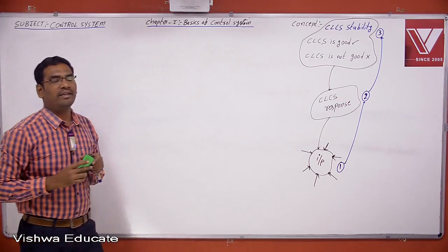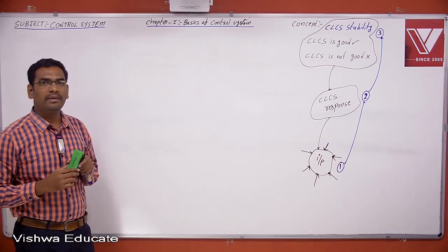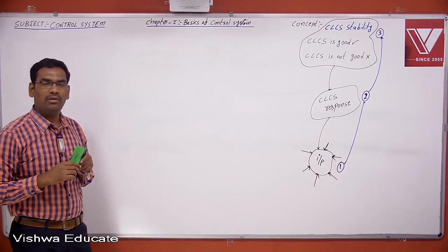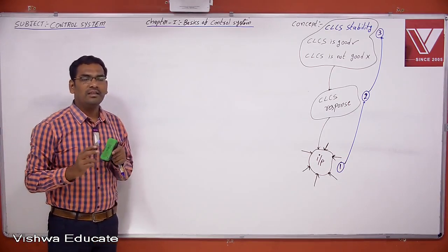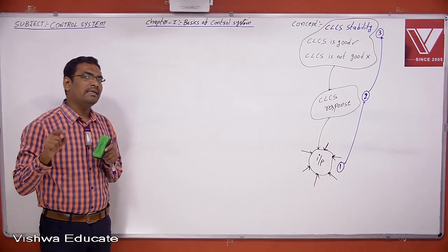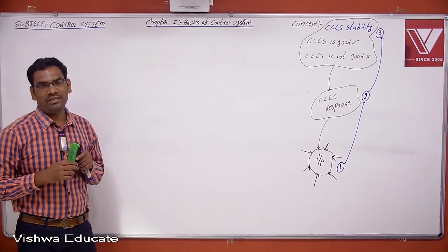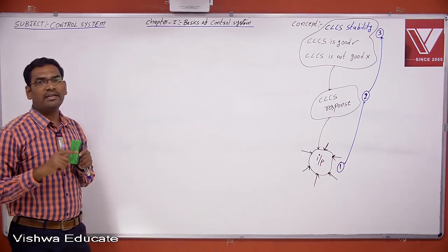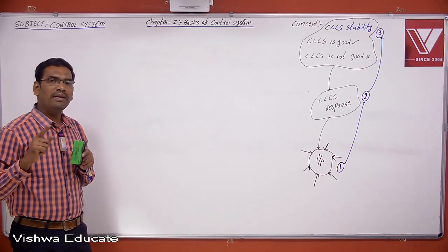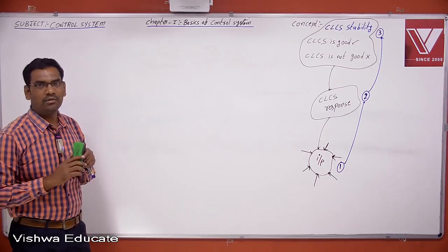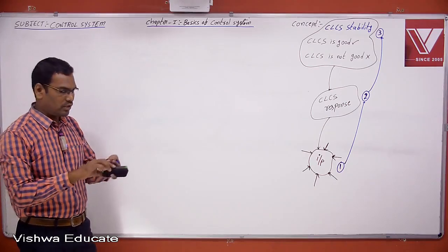In which case can you get an accurate output? Can you get an accurate output in the case of open loop control system? No, there is no error generation, there is no error analysis. The error generation and the error analysis are available in the closed loop control system. Therefore, the closed loop control system will produce the accurate output, because the controller will continuously apply the controlling action as long as error becomes 0, which we already covered in the previous sessions.